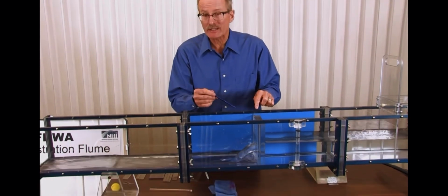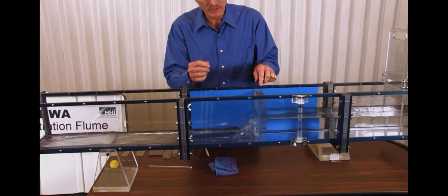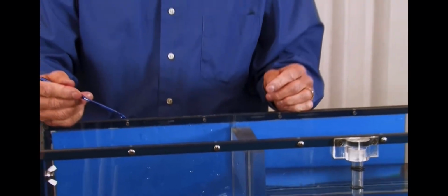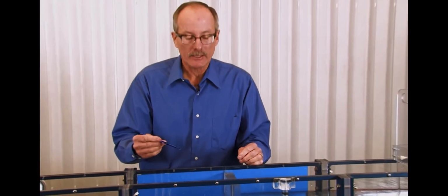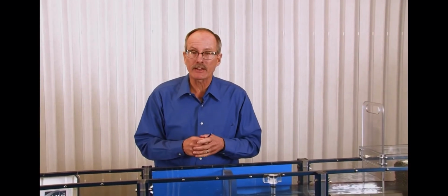If we look at the jet diameter again, you can see part of the reason that that's occurring. If I pull the rounded orifice out, that jet immediately contracts, and we're not making full use of that area. As soon as I put the rounded orifice in place, the jet expands to nearly the opening of the area, and the headwater's lower.